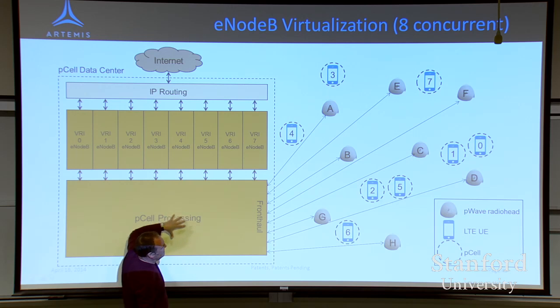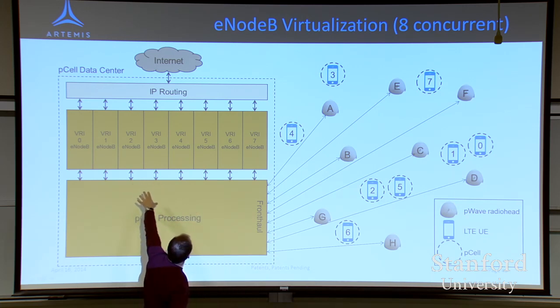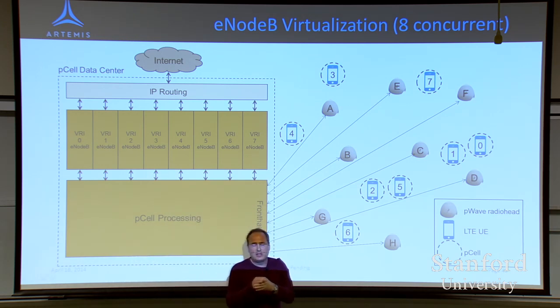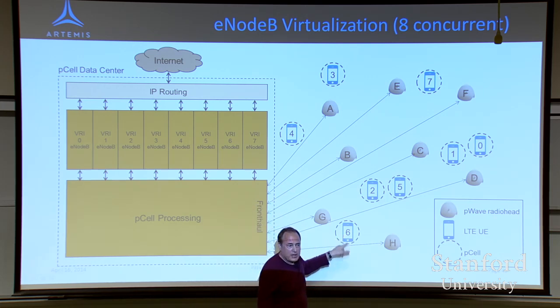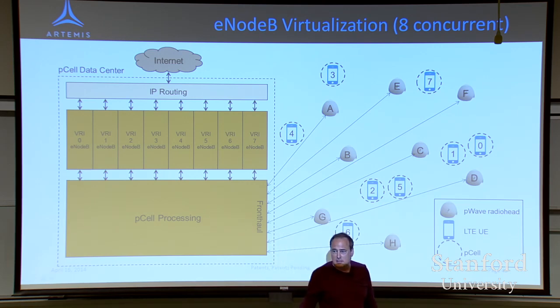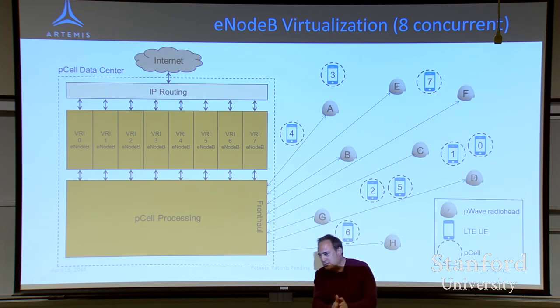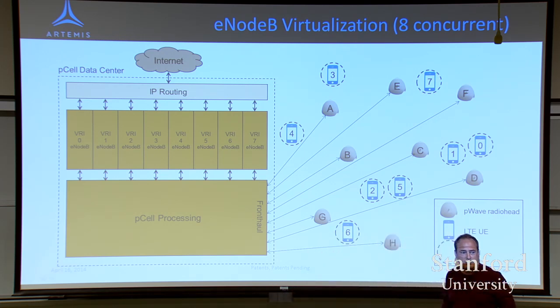They feed into here. And then through this processing, we do a spatial mapping between one of these eNodeBs and a device. For example, VRI3 appears at the receiving point of the antenna of user device 3. And VRI6 appears right here, okay? And literally, if you take a piece of LTE test equipment, that's what it shows. It will actually show that, I'm all alone here. There's no one else using any of the resource blocks, and I have the full channel to myself, okay?